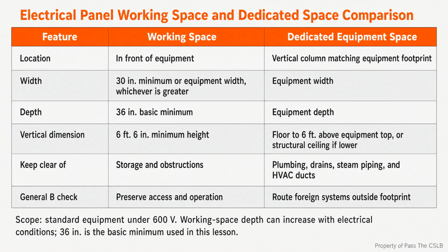Before inspection, I coordinate the qualified electrical subcontractor, the tool, and any required verification, rather than discovering at the inspection that the work cannot be demonstrated. Temporary power belongs on the same readiness check. On a construction site, all 120-volt alternating current, single phase, 15 ampere and 20 ampere receptacle outlets used by employees and not part of the permanent wiring require approved ground fault circuit interrupter protection.